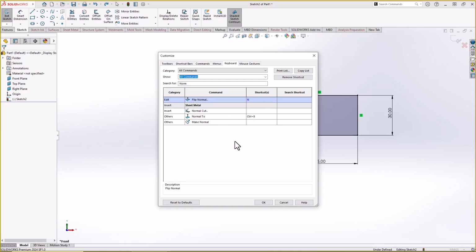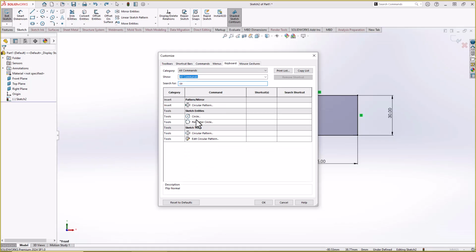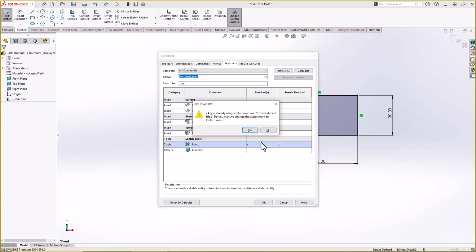Similarly, circle. Center circle, if you search CIRCLE. In the circle, I'll press C for this. And similarly for trimming, trim. This is the one I would like to have, not E, I would like to have it as T. Trim is done. So what else?